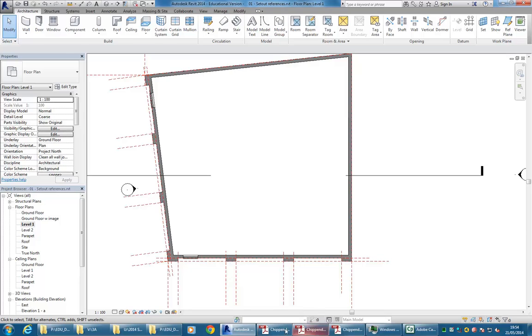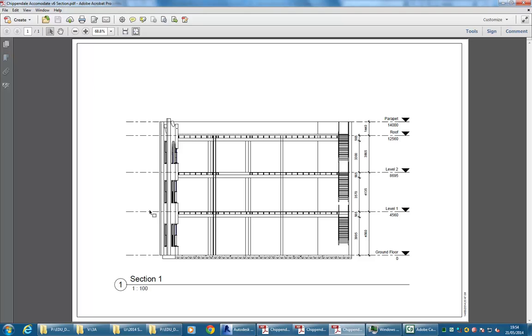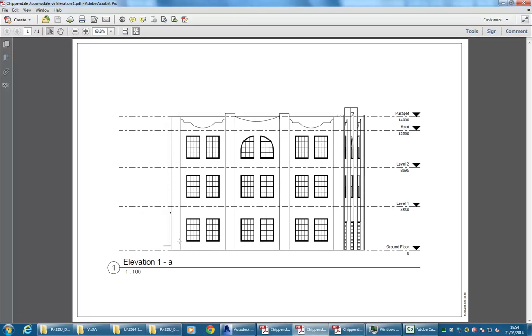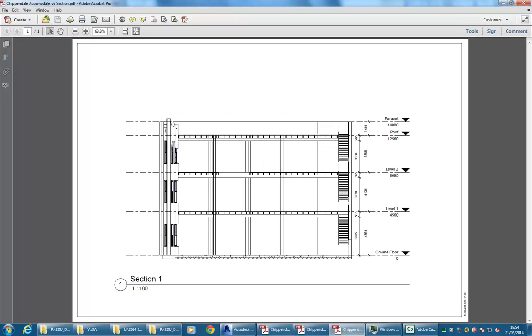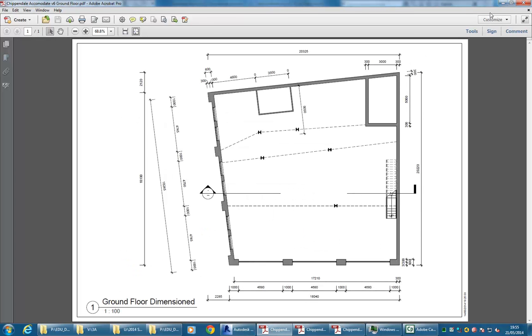And then looking at the floor plans, you can see the spacing there is only very roughly given, and I'll show you how to work that out in a second. But then in the section and the elevations, I was going to say you should be able to see the sill height, but I haven't given you a dimension. So let's just see if I can eyeball it. It's about 700 anyway. I can just see by eye there, maybe a little bit higher, but it's a very easy thing to adjust if the sill height needs to change. So I'll leave it at 700.